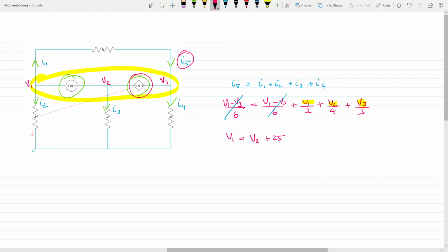Now we do the same thing for this other voltage source here. This is a dependent voltage source. The amplification is 5, and it depends on the current, specifically the current I2. So to write that out, V3 is equal to V2 plus 5 times I2. Now I'll just sub in for I2. I2, I think we found, was V1 over 2. Yep, V1 divided by 2. And so let's scoot this guy down off to the side. We don't care about it. Delete this. Scoot this back up.